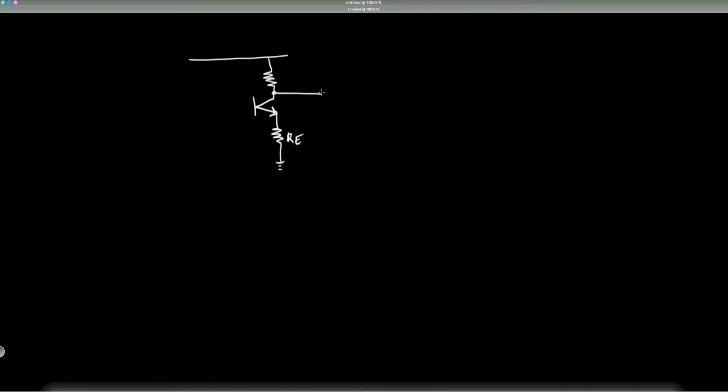In other words, we're coming out also from here, and this would be our expected AC output, this being RC, the circuit being fed by a positive DC source, a typical voltage divider, with an input resistance feeder to control the voltage level at the base, this being the collector, this being the emitter, and an abstraction of an AC source, small signal, to this common emitter single stage. And this would be our Vin.